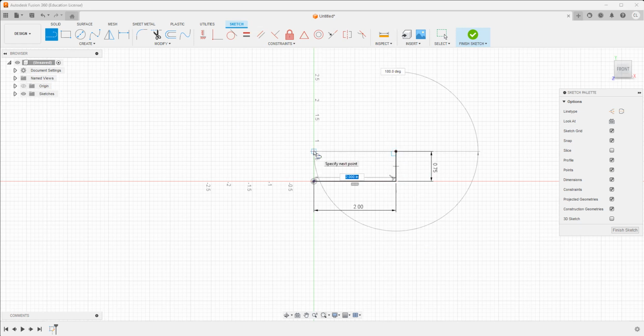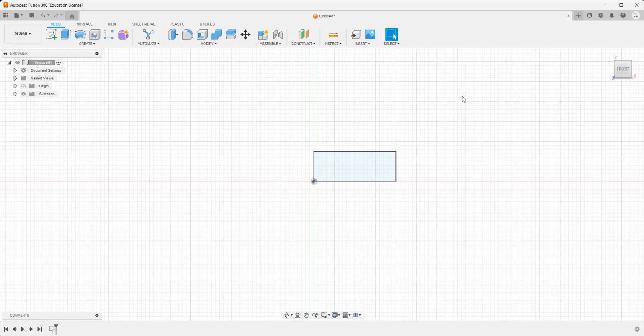This one is going to magnetically attach to the y-axis because I have another reference point right down here. So if I just drag it across, it will magnetically align to that point above it. So I'll click there, and then I will complete the closed loop. Okay, so now you'll notice that once I do that and I deselect the line tool, hitting escape on my keyboard, all right, I'm going to go ahead and click on Finish Sketch.